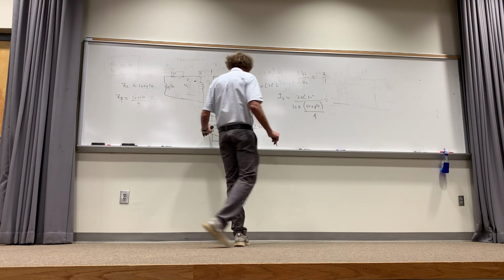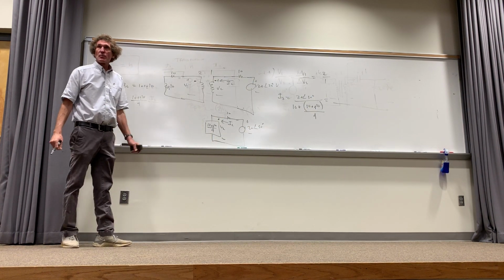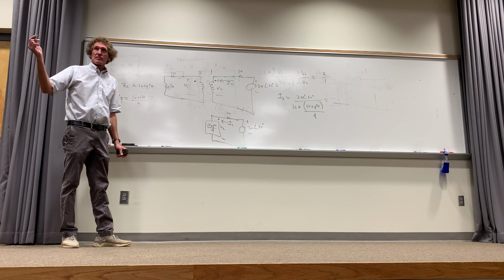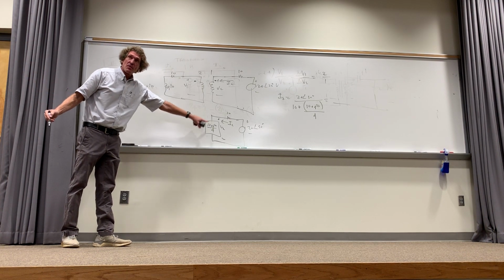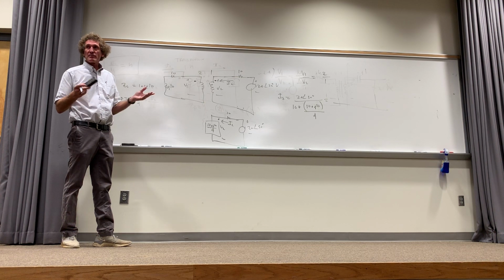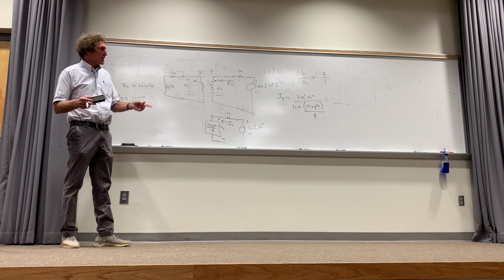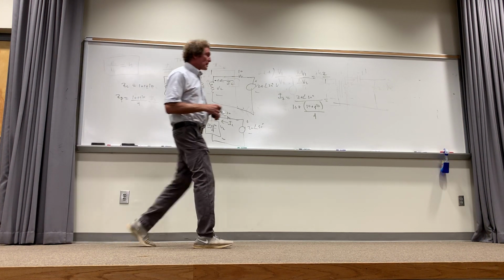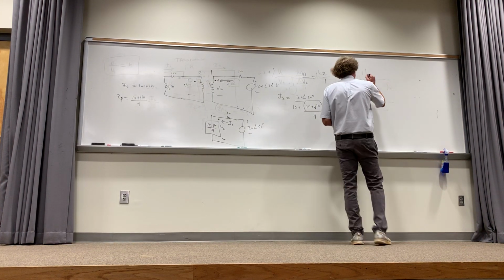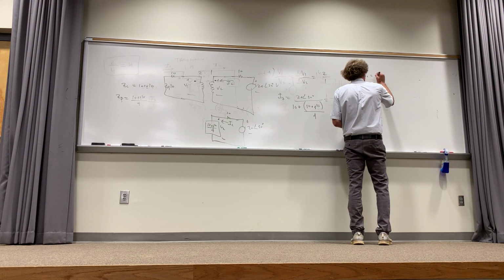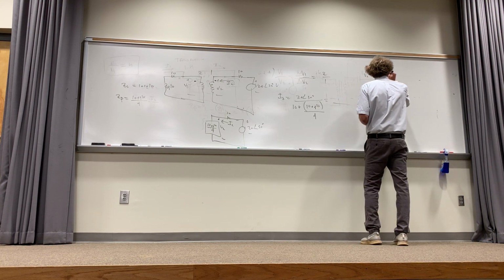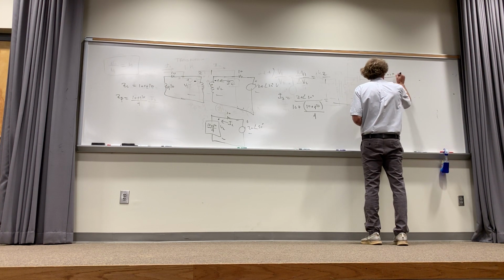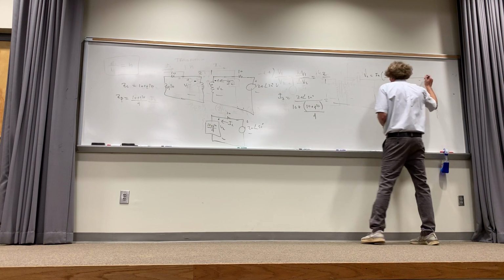It's simply this number here. I'm just showing you where it came from. It comes down to 2.5 plus J2.5. Now, that's going to be that current, you all agree? What is V2 going to be? V2 is going to be I2 times 10 plus J10 over 4, or 2.5 plus J2.5.